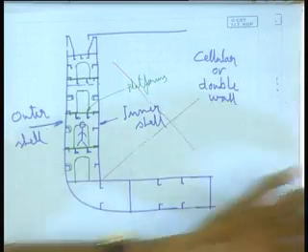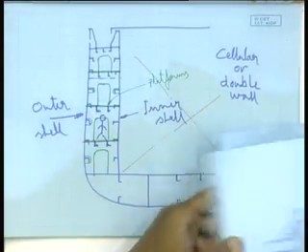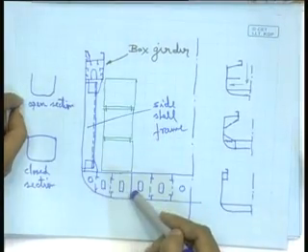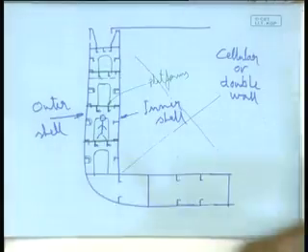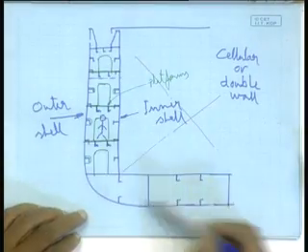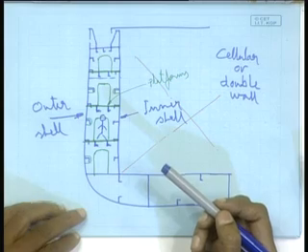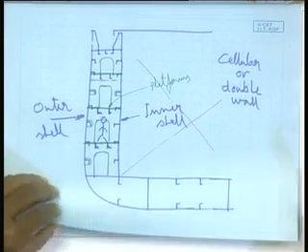So, we can see that here, if it is a box girder kind of arrangement, then we take a combination of longitudinal framing system and transverse framing system. If it is a double wall construction, then it is all longitudinal framing system; there is no transverse framing system taken, right. Okay. So, we stop here today.